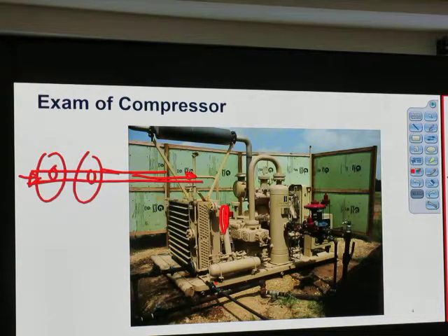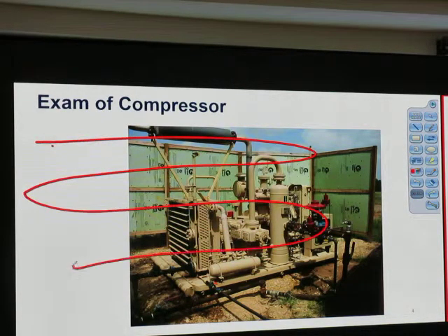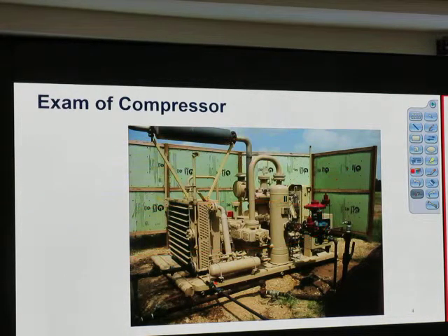Because if we have a long pipe and we flow gas in, we will have pressure drop. Flowing in a pipe, we always have pressure drop, so we need to have a big enough size. Number two, every turn, like in this interstage cooler, there will be pressure drop. The pressure drop could be 2 psi, 5% or something. So it's not really constant pressure.